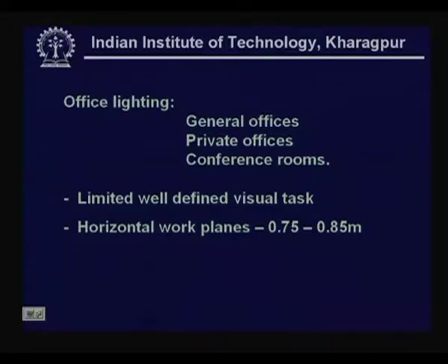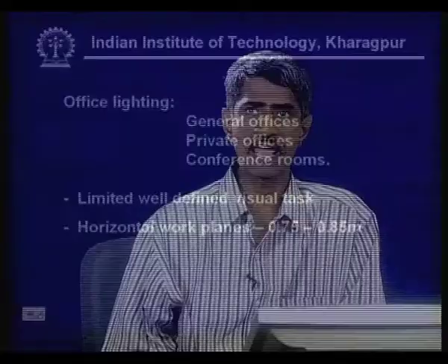That's why most of the commercial packages available for lighting calculations assume a work plane around 0.75 to 0.85 meters. The only situation where the work plane is assumed to be vertical for interiors is in a classroom, for the teacher to write on a chalkboard or a screen.